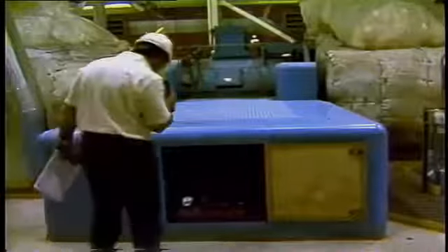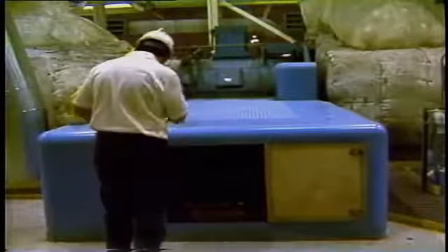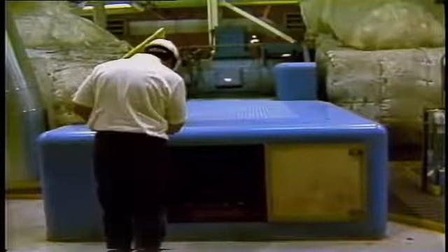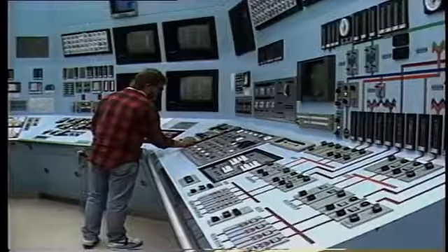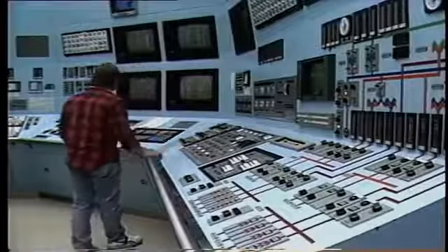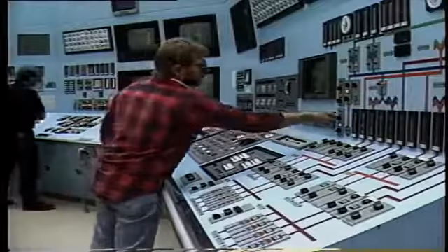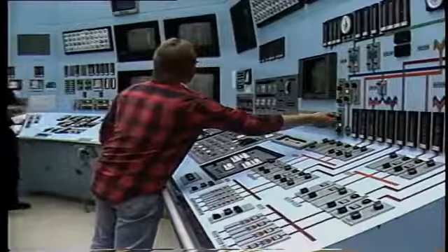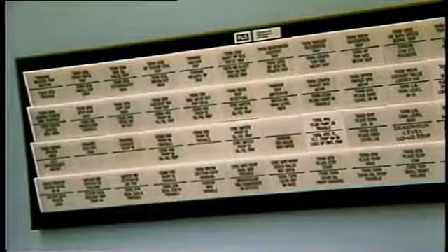Most of the turbine operations are performed remotely from the central control room, with the support of regular local inspection by a roving operator. In traditional control rooms, the operator works at a large panel which includes switching controls, indicating lights, indicating instruments, and recording charts for the complete unit, that is, boiler, turbine, generator, and auxiliaries. The annunciator panel, usually located above, provides indication of any alarm conditions.